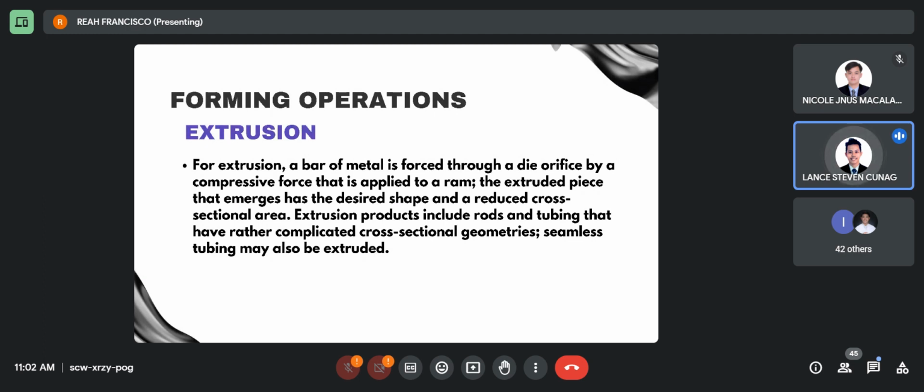In contrast, cold extrusion performed at or near room temperature is suited for materials that are not as malleable when heated. Industries such as construction, automotive, and electronics utilize extrusion to manufacture an array of products, including aluminum profiles, pipes, wires, and structural components.